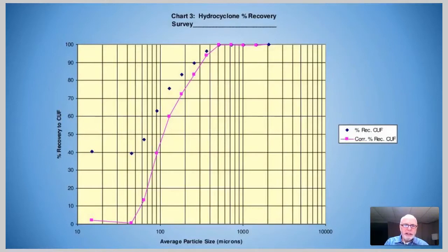And this is a high efficiency cyclone, one of the newer designs created by the cyclone manufacturers over recent decades with the aid of CFD and so on. These cyclones give a sharper overall separation performance than older design cyclones.